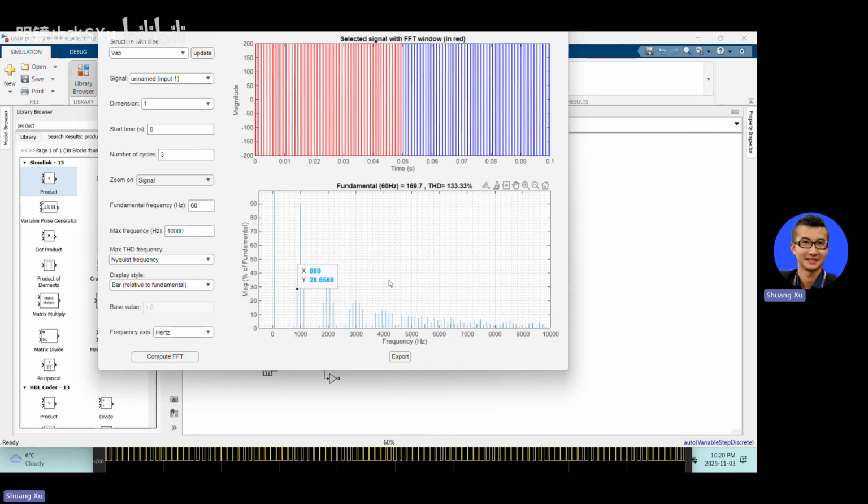So this THD is different, and we can see the THD is higher than that in the unipolar SPWM. That's also what we discussed in the class. The bipolar SPWM has higher harmonics than unipolar SPWM, because it makes the current increase and decrease with larger current ripples. So it has higher THD. So that's the bipolar SPWM.